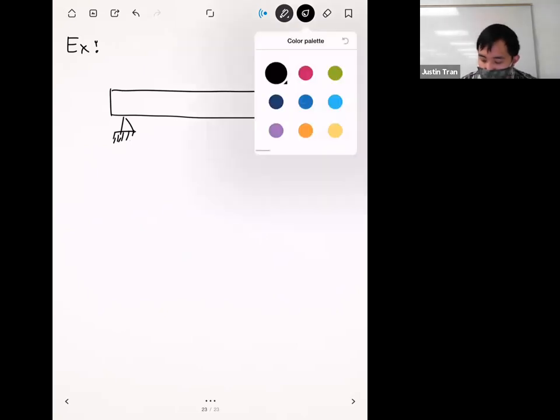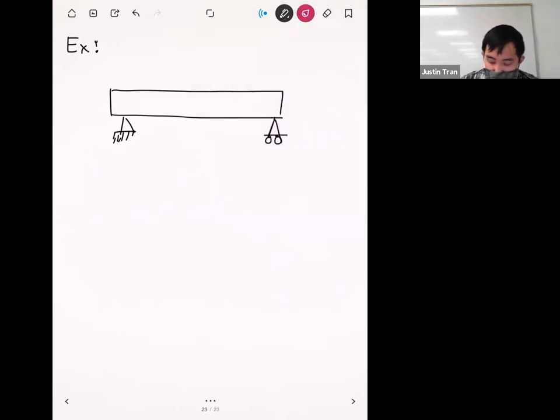If you want to displace this beam, you would apply a force on the right side, a horizontal force on the right side, because that's where the roller is. But if you try to apply a force right here, okay, on the side where it's pinned to the ground, nothing's going to happen, right? So there's no way for that force to transmit to the rest of the beam because it's just hitting that fixed support. Okay. And so here, what you have is both a load and a fixed support at the same time.